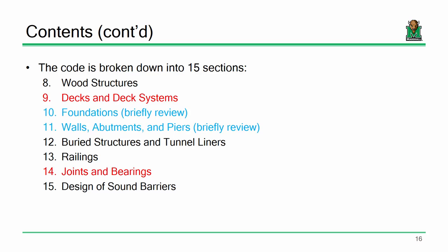Okay. Now, decks and deck systems, obviously we need to talk about that. When we actually do deck designs, though, a lot of this is sort of done for us. We use a different method called the empirical method. There's really not much design. You just look at it and go, here's how much rebar you need. I'm not kidding. It's basically that simple.